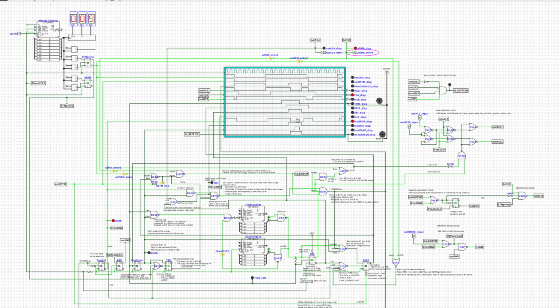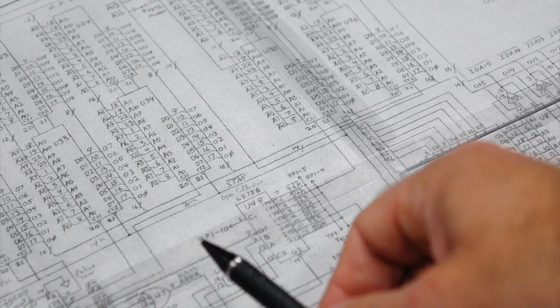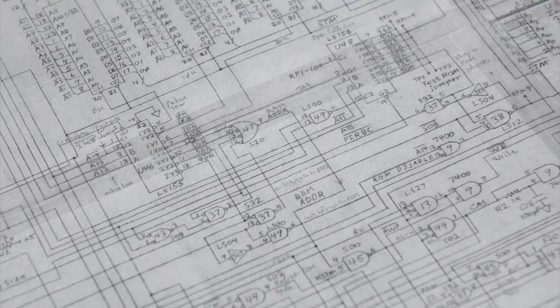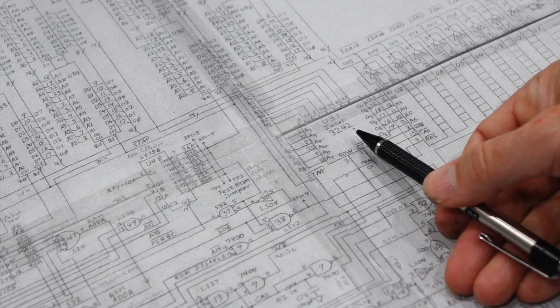All of a sudden I realized that, oh, maybe we were all frazzled by these machines reacting completely differently. And maybe the refresh logic works, it's just that one is stuck in one refresh mode and the other one is stuck in the other refresh mode because of the processor activity. So all of a sudden, I started to suspect a completely different part of the circuit. It's either something in the devilish logic here, or something could happen with our little memory controller.